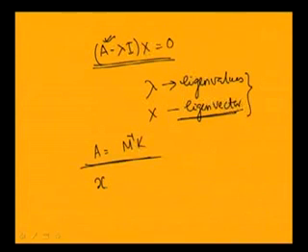Already we have seen in the case of a 2 degrees of freedom system, the resulting free vibration x at any time t can be written as C1 phi 1 plus C2 phi 2, where phi 1 and phi 2 are the normal modes of the system and C1 and C2 are the modal participations in the resulting free vibration, which depend on the initial conditions.